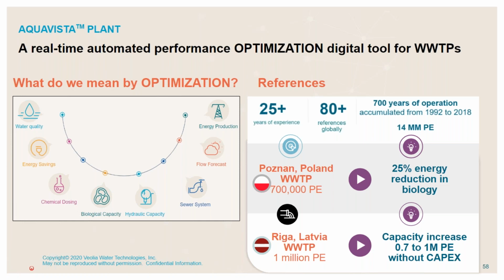There's a growing library of modules. So there's, for example, a nitrogen module. There is a StormFlex module. The StormFlex module fully controls the sewer system, with SewerFlex as a part of that. It controls how flow is received at the plant, and how pumps operate in the collection system, based on a variety of inputs, including weather radar data, to really prepare for storms and be proactive.